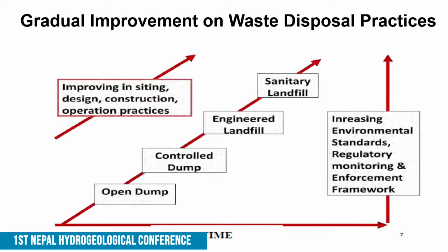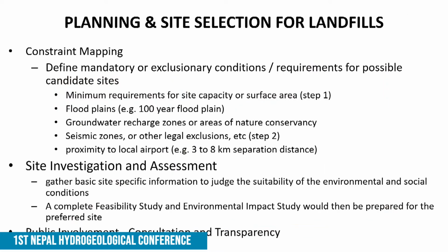Then we need proper design, proper construction, and finally the operation should be as per the guidelines we have prepared for sanitary landfill site operation. At the same time as we improve technically, we have to increase the environmental standards, as well as the regulatory monitoring and enforcement framework. When you work together on both sides, then we can convert dump sites to engineered landfill sites.